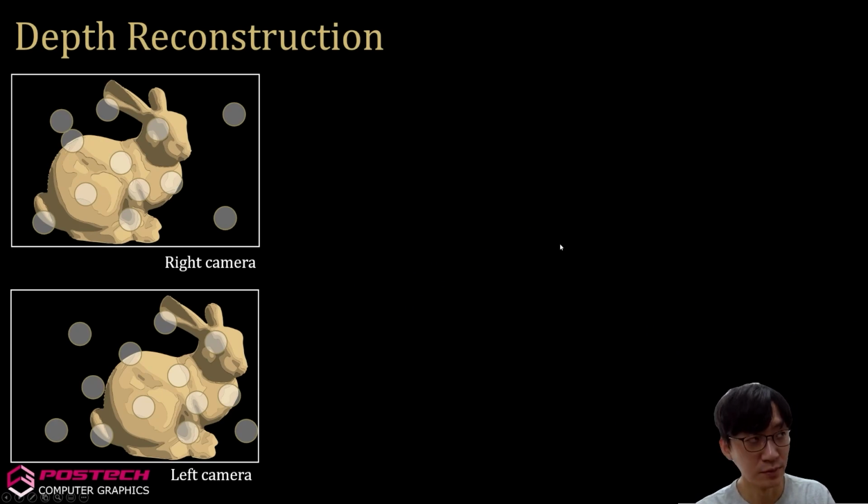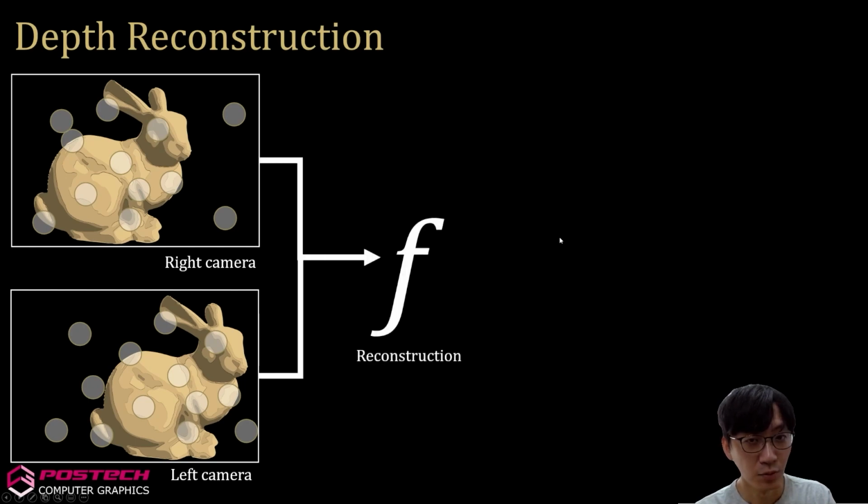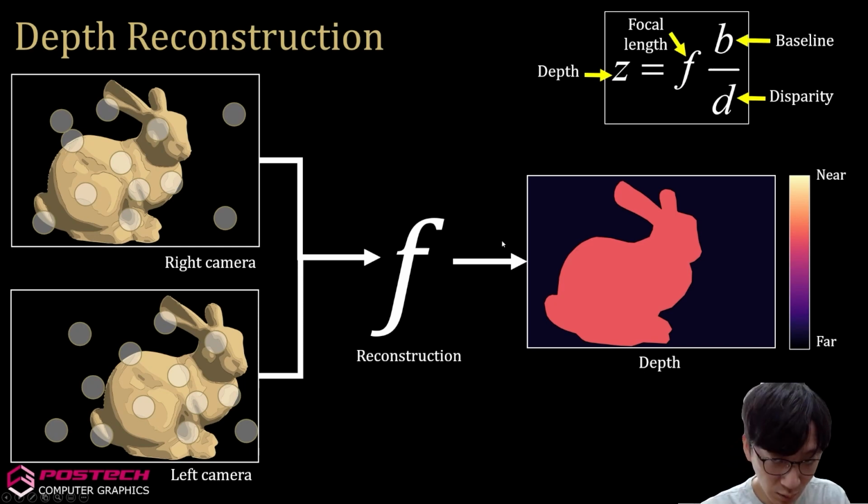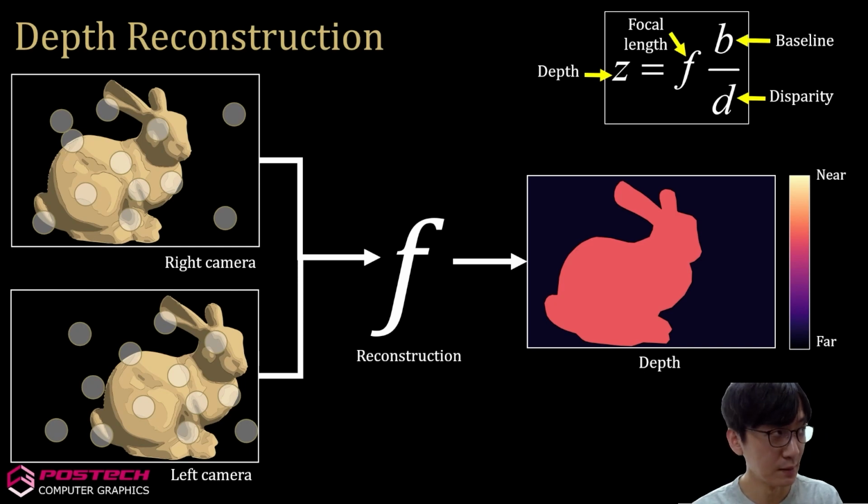The captured images from the stereo cameras now contain both scene texture and illumination patterns on top of the scene, right? Then we estimate the depth information by matching correspondence between these two images. Since we have additional illumination projected onto a scene, we can make use of it in addition to the scene texture to build this correspondence mapping, which is converted into depth information for each pixel. So this reconstruction algorithm makes use of both scene texture and illumination pattern.